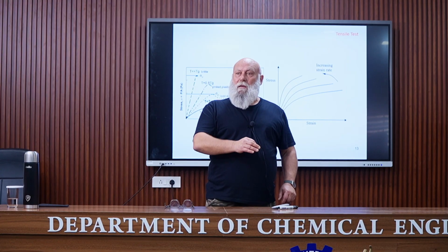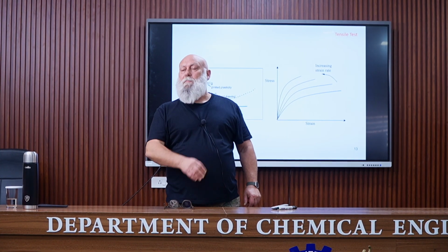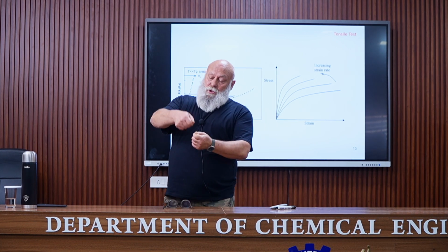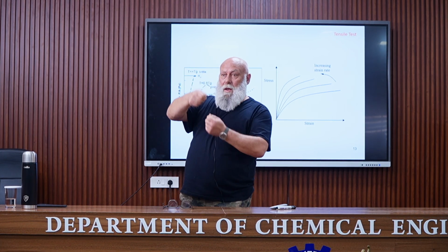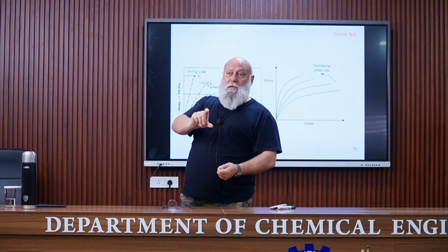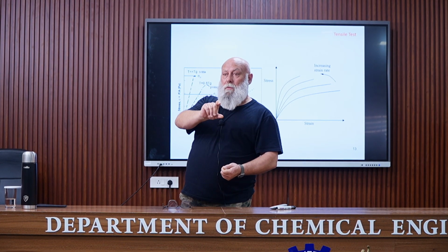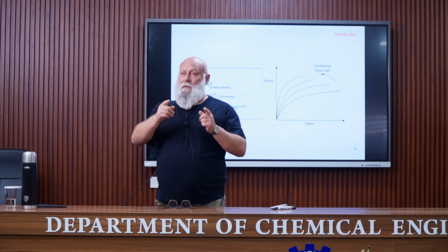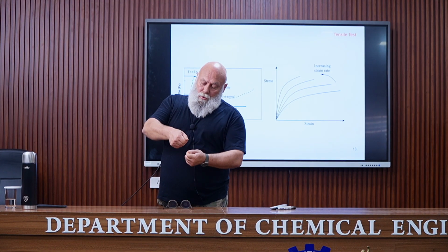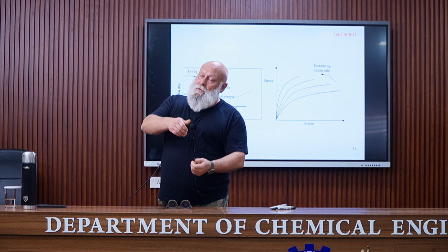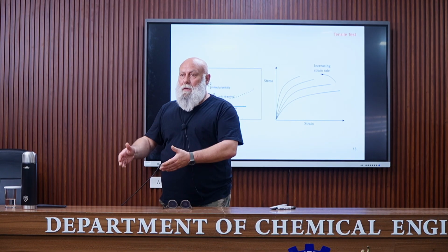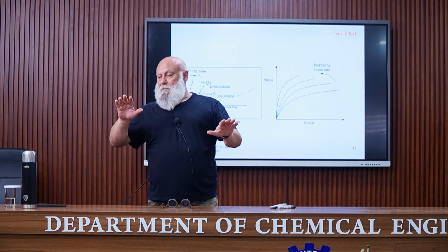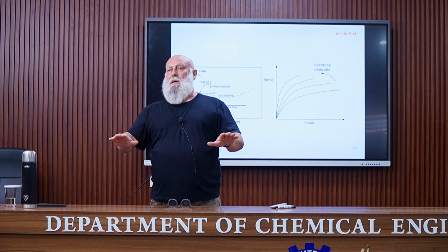Now there is another time which is characteristic of the experiment, which is the experimental time. If you stretch your material rapidly, the duration of the experiment is short, so the experimental time is short. If you stretch slowly, the duration of the experiment is longer, the experimental time is longer. You need to compare this experimental time and the relaxation time.